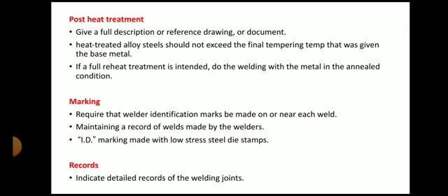Then post heat treatment. After welding, sometimes post heat treatment is required. So what kind of heat treatment you are going to perform, the description of that heat treatment you have to mention in your document. Then heat treated alloy steel should not exceed. So these are some information about the heat treatment, which you have to mention in your WPS.